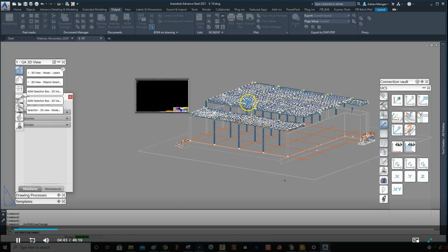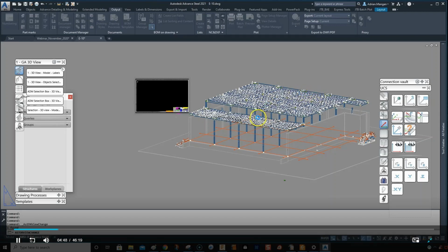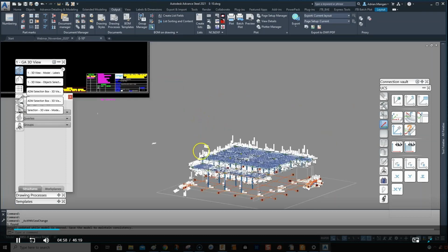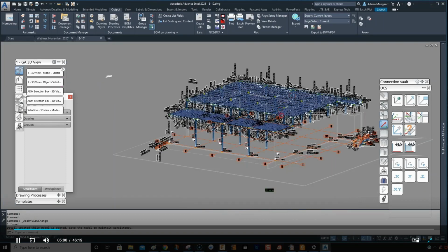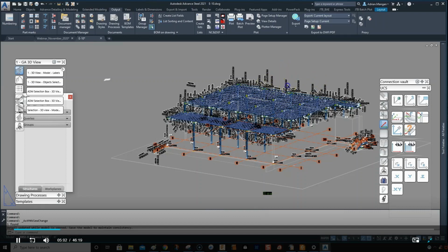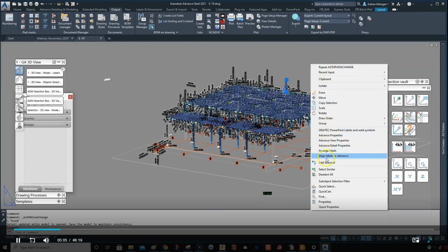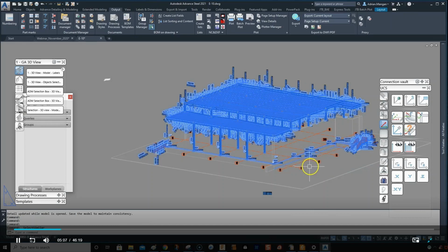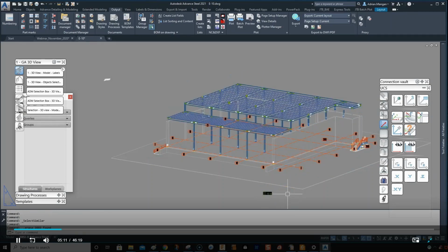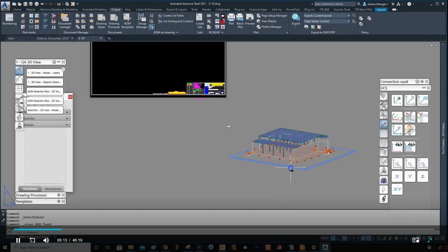Realistically, you're not going to go through and select the ones you want to delete. You're probably just going to select them all, delete them all, and then re-enter the labels for the beams on the outside, which takes time. This is the way I did it when I didn't understand it a little better. So if I select that, then select similar, and then deselect the title and delete, I can delete all those.